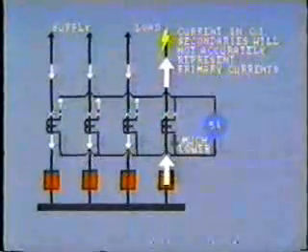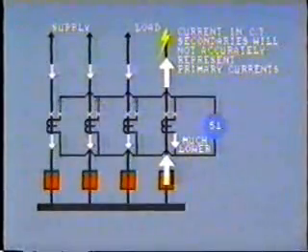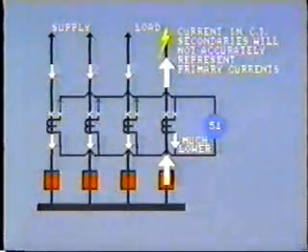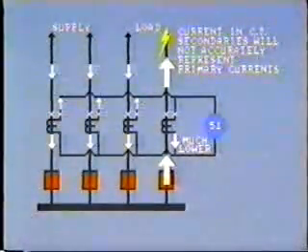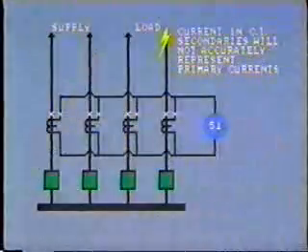The secondary current on this saturated CT will be much lower than the sum of the secondary currents of CTs 1, 2, and 3. The resulting imbalance would look like a bus fault and cause the relay to operate. This imbalance in secondary current is greatly exaggerated during the first 15 to 20 cycles of the fault.